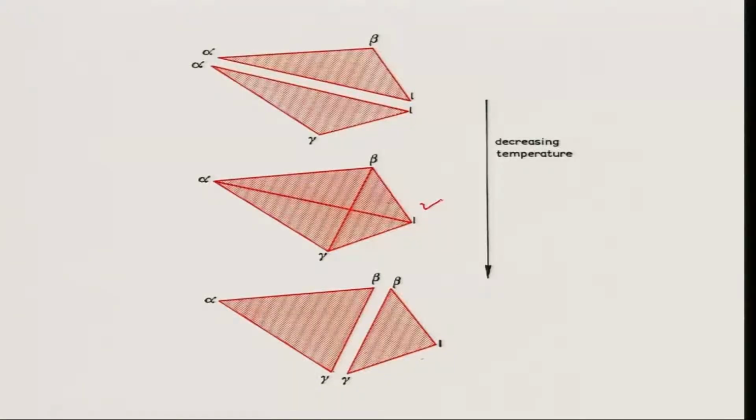And not only that, as you decrease the temperature, the exit from the ternary 4-phase equilibria will happen with two 3-phase equilibria again. One of them is alpha, beta and gamma, the other one is beta, alpha and gamma, correct. The important characteristic feature of such a quasi-peritectic 4-phase equilibria is that there have to be 2 monovariant reactions which precede the invariant reaction, correct. That is the most important criterion.